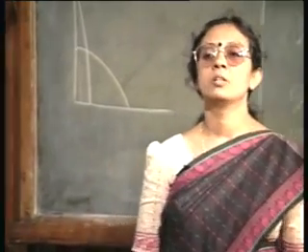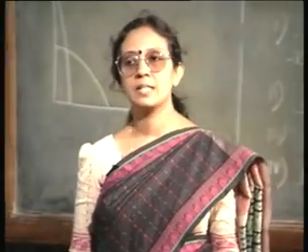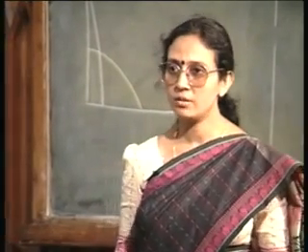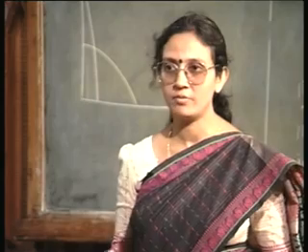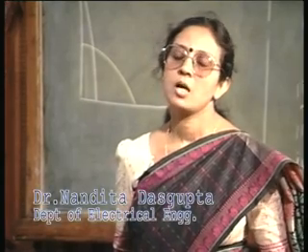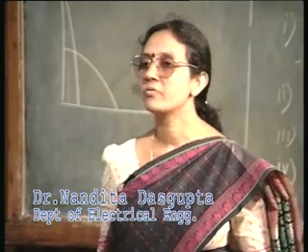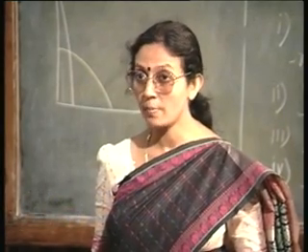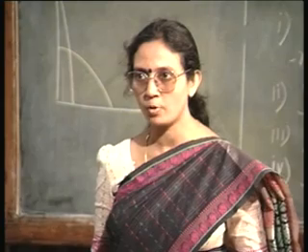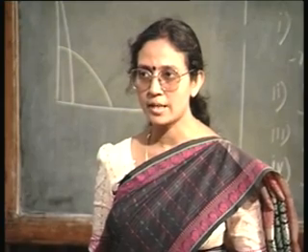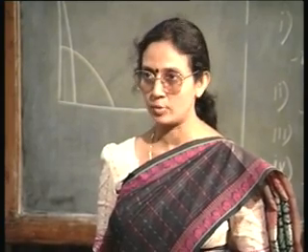Fortunately, for silicon, these annealings are done at comparatively lesser temperature, by 950 degrees centigrade, as I said. So, at that temperature, the square root of Dt is not very high, it is quite small. Remember, the square root of Dt is a very important parameter, right. This actually determines the diffusion depth.